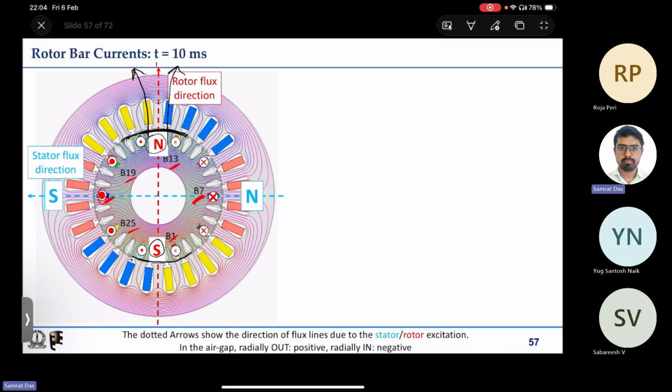Now if you remember the field polarity at t equal to 10 millisecond for the earlier case, that is when speed was 2400 rpm, it was the opposite. And if I plot the field the way we plotted last day also, theta, this is 180 degree, this is 360 degree, obviously 0 degree, 90, 270.